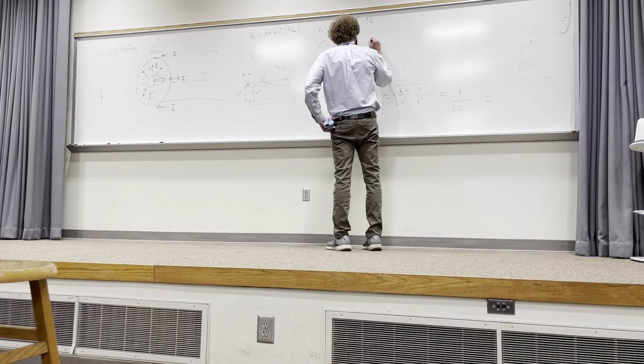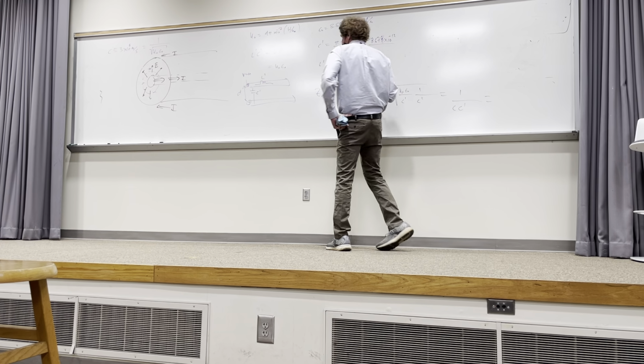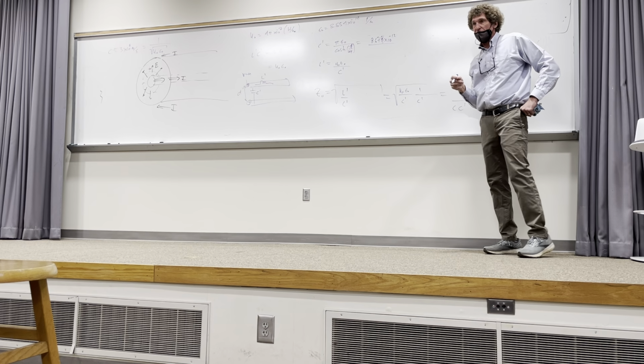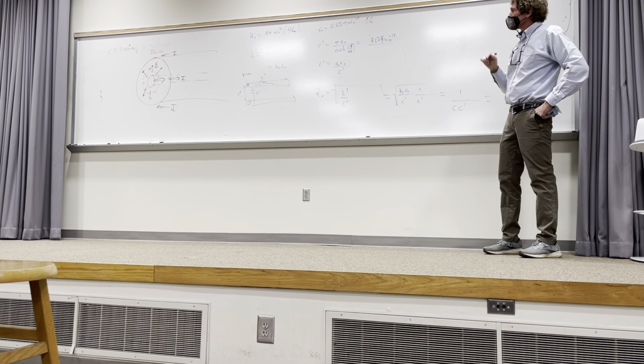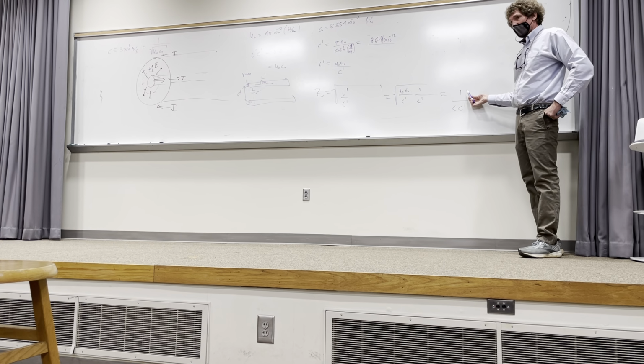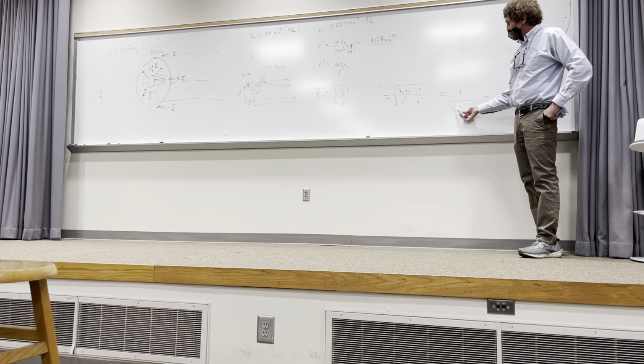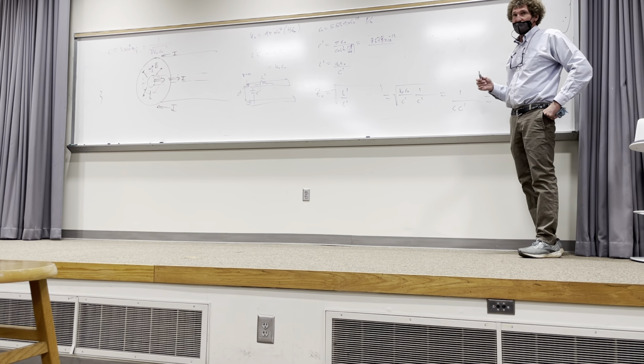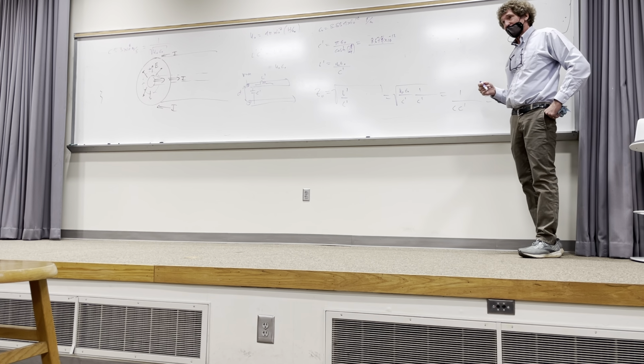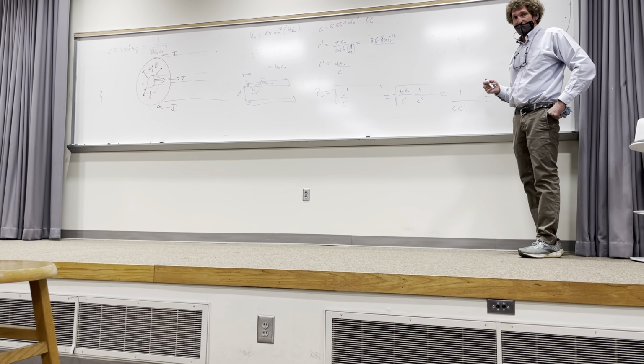8.678 picofarads per meter, I believe. 678 times 10 to the minus 12. That's fine. That would be farads per meter, but this is fine, 8.678. Now, if you take that, take 1 over the speed of light, which is about 3 times 10 to the 8th, times that, take 1 over it and tell me what you get. And that should be the characteristic impedance that's given in the answer, if we didn't mess this up, if we didn't fudge too badly.